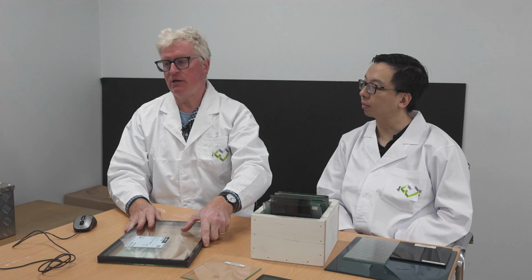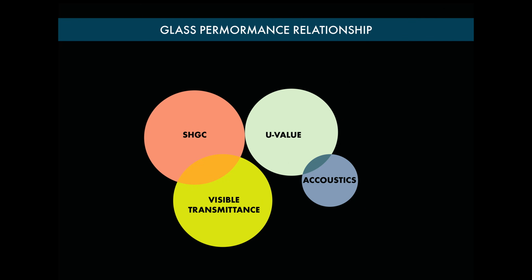So the three components, the solar transmittance, the absorbed solar radiation that is admitted into the space, and the U value, all make up the performance of a glazing system. When we talk about high performance glass or windows, the first thing that comes to mind is double glazing, and it's all about how we stop the heat loss at winter night. What can influence the property, Mark?